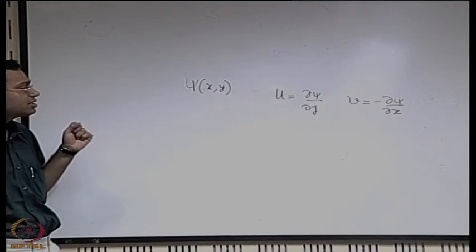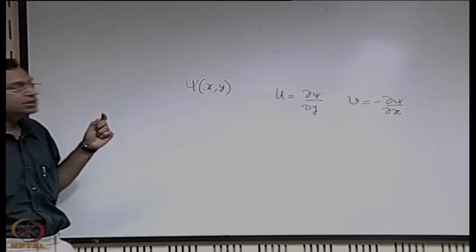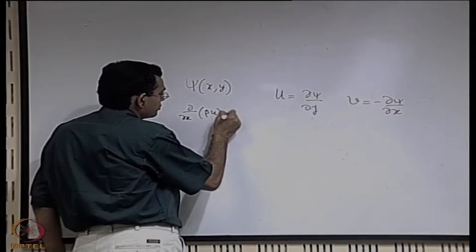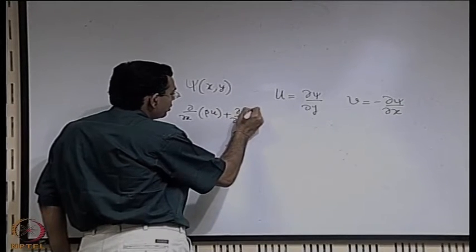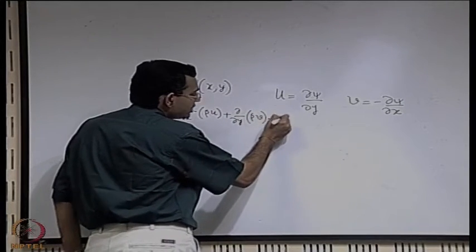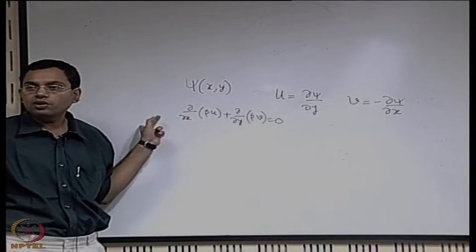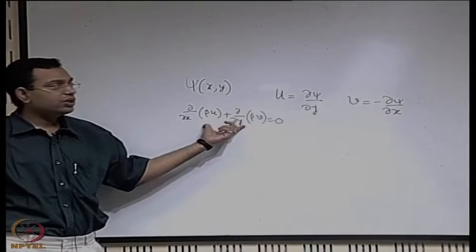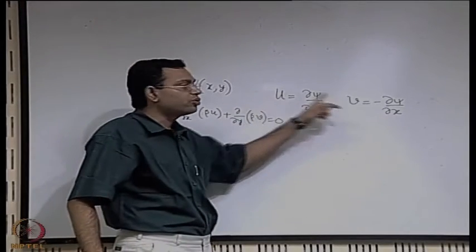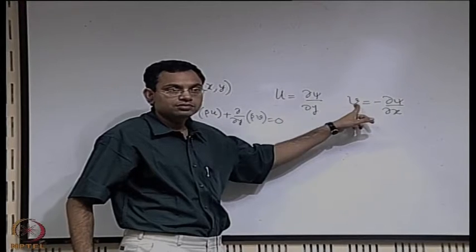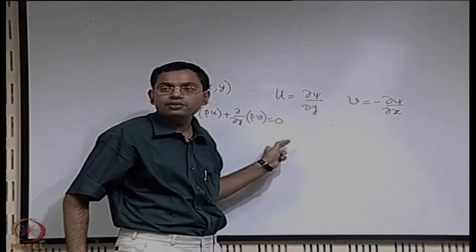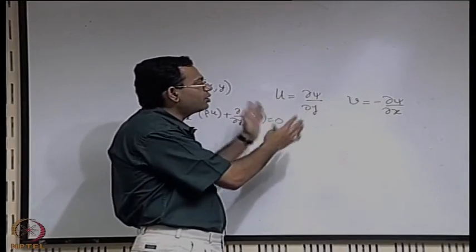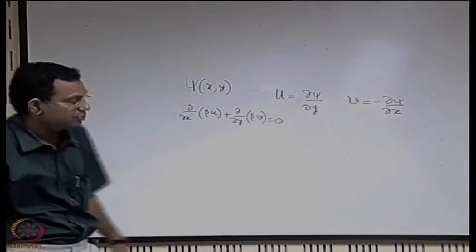When you say a two dimensional steady flow, your continuity equation becomes different, whether rho is a constant or not, based on that it will come out of the derivative or not. So, this is a bit more general case than the case that we had considered, and for this also it may be defined, just replace u with rho u and v with rho v, then the similar parametric form may be defined. So, it is not that this is a hard and fast rigid definition, but this is like a definition for the most common case that we are talking about.